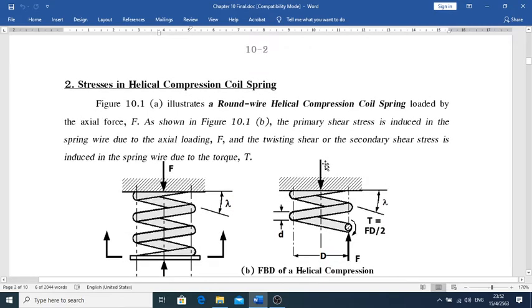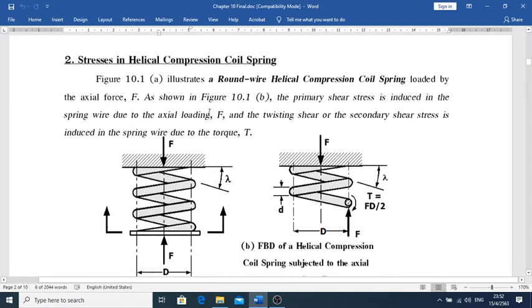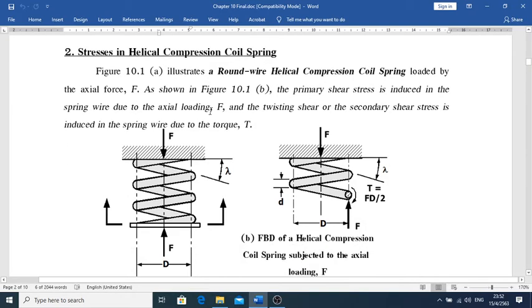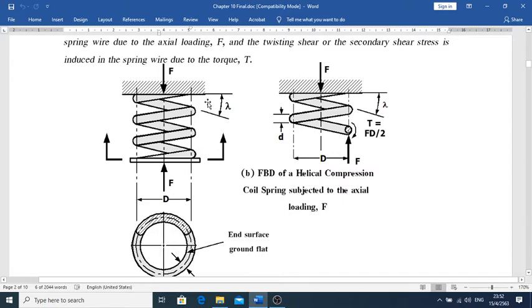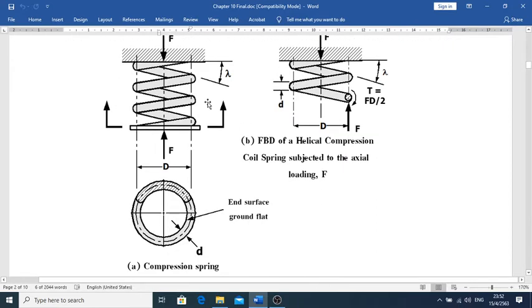And then let's go for number one, the helical compression coil spring. Okay, let's get started with this type of coil spring. We employ this type of coil spring a lot for compressive purposes, and we use this type a lot in automotive applications. We have a coil that looks like this. We have a diameter of capital D, and a diameter of the spring wire of small d. And then we have a lambda, which is the angle of the coil.